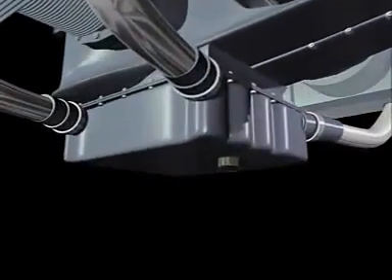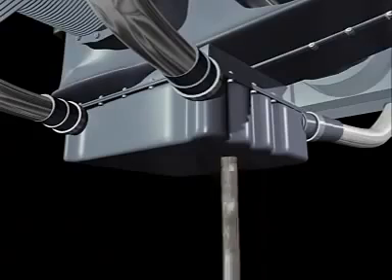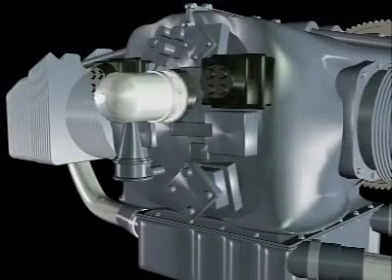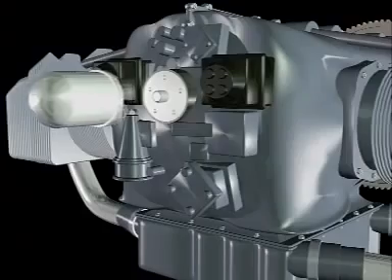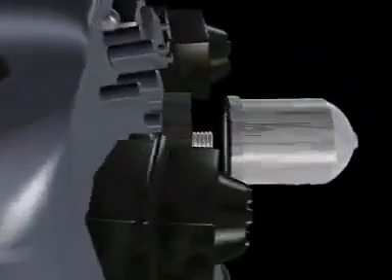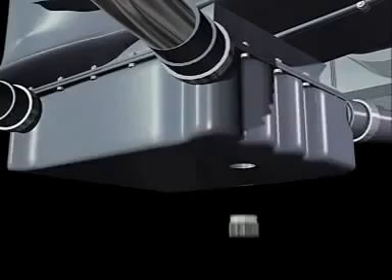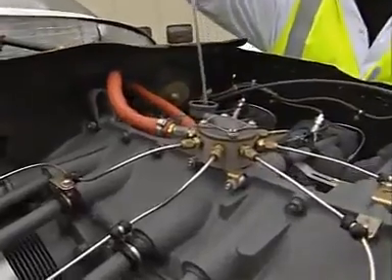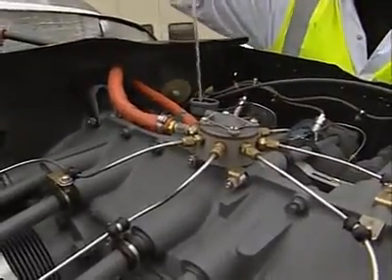First, the oil sump plug is removed and the old oil drained from the engine. Next, the oil filter is removed and replaced. Once the new oil filter is attached and the sump plug put back into the engine, the fresh oil of the correct grade can be topped up through the fill point. The fill point also contains a dipstick to allow regular monitoring of the oil level in the engine.